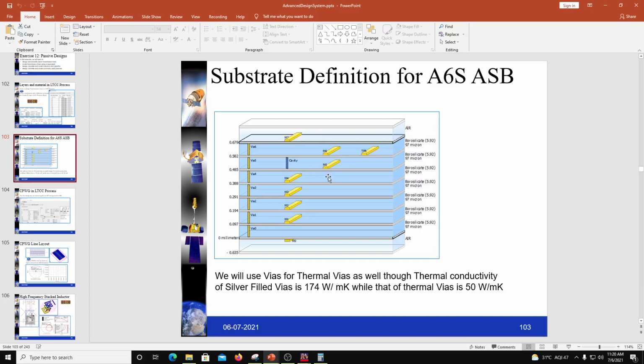Okay, or you can choose M5 and M6. The distance matters, it is 97 microns. So M5 and M6 are going to be a strip line, while M7 is a microstrip line because it has air on the top and the substrate on the bottom. The way we did a line cal is for a microstrip, not a strip line, right? So I'm going to draw this on M7.